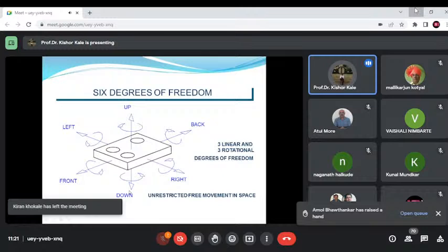This part can also be rotated along the axis, and then you can see this part shown over here. This is called the stylus. So CMM probe stylus for CMM machine tools, ceramic stem, and then 6 mm. Ruby ball tips are used generally.